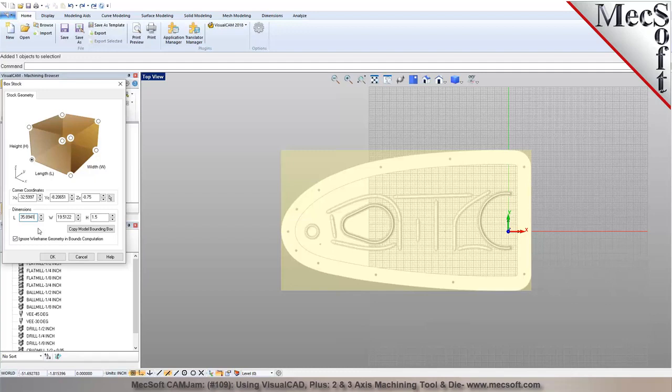So here you said you want to do 3/4 inch on each side, right? Is that correct? Yep. So I'm going to add 1.5 inches, so basically it'll add 3/4 for each side. I'm going to do the same thing in the other axis, I'll say plus add 1.5 inches. That is 3/4 times 2, and then I'll leave this as 1.5, and I'll pick OK here.